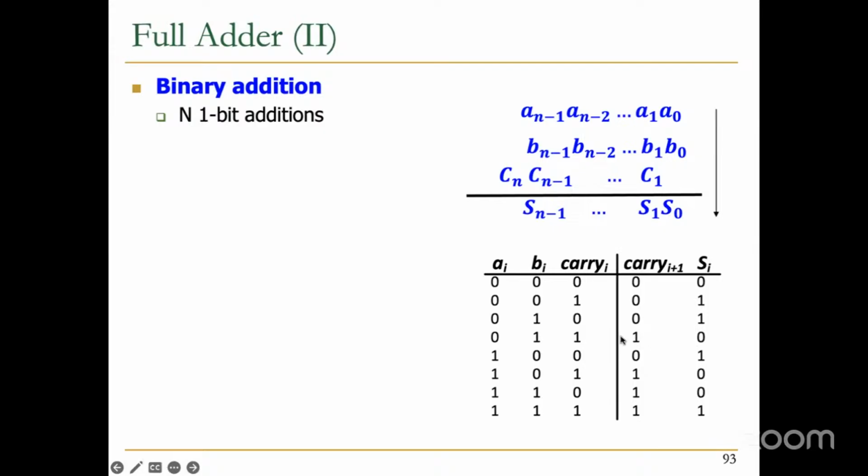So this is what it is. So that's correct. But you can verify all of these. So if you want to do an n-bit addition, you really do n one-bit additions, right? You do this bit, generate the carry, and then you do these 3 bits, and then generate these, or this bit, and generate the carry. So it's really a sequential process, basically.